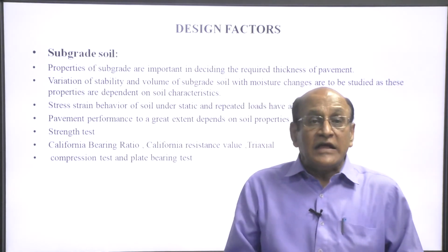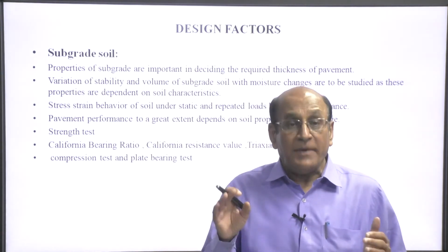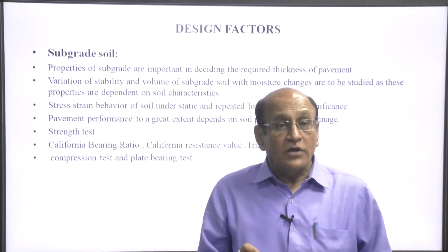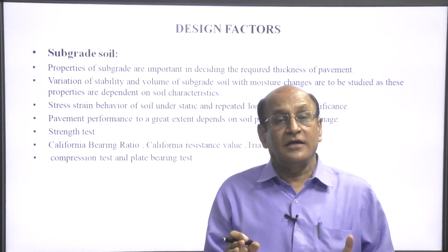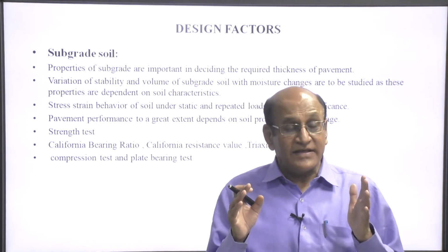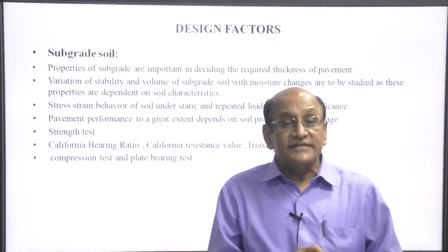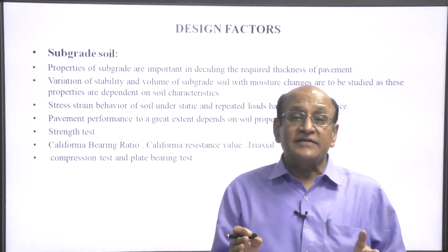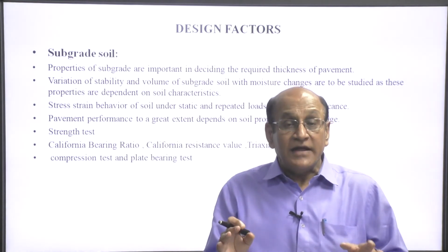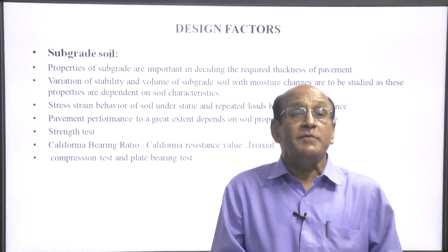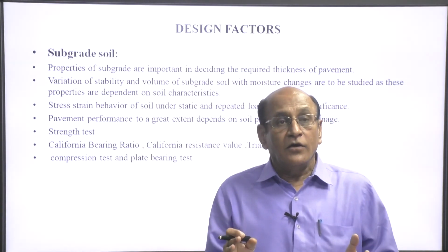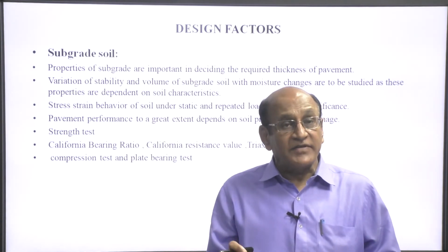And fourth, it provides a cutoff for capillary water coming from the bottom to the top. So, these are the basic requirements for the subgrade. Subgrade is not a neglected item of the pavement system, but one of the most important factors, because this will decide how the load coming on the pavement surface will behave.